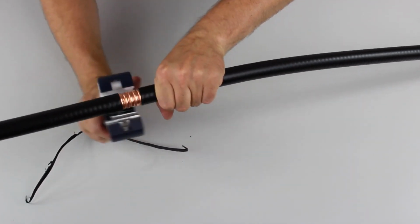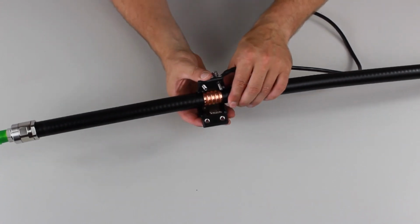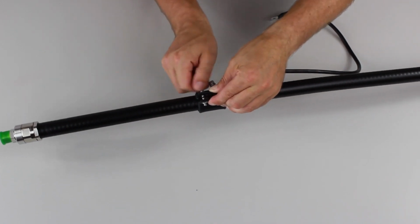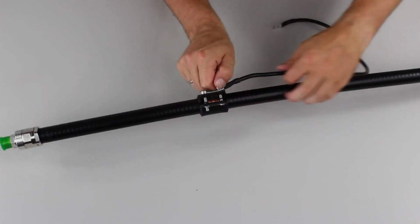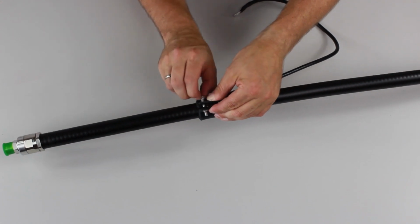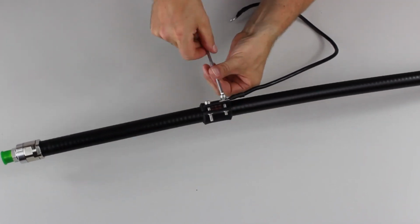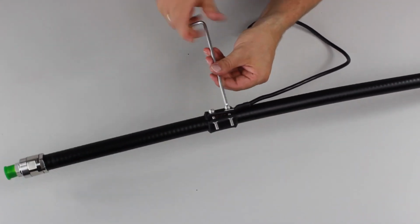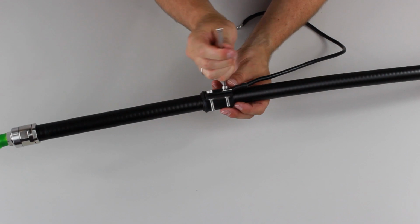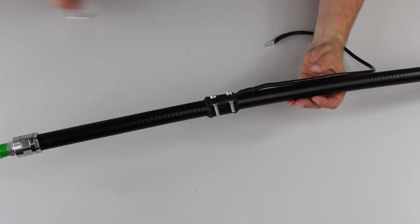First, place the contact elements of the grounding kit on the stripped cable, making sure that the cable is lying exactly in the middle of the contact surface. Try to push the two grounding kit circuit boards together as far as possible and turn the screws. Then push together tightly until the circuit boards are completely closed and you are able to tighten the screws by hand. Now, screw the screws into the thread with the Allen key. In its final state, the rubber component must completely enclose the cable.